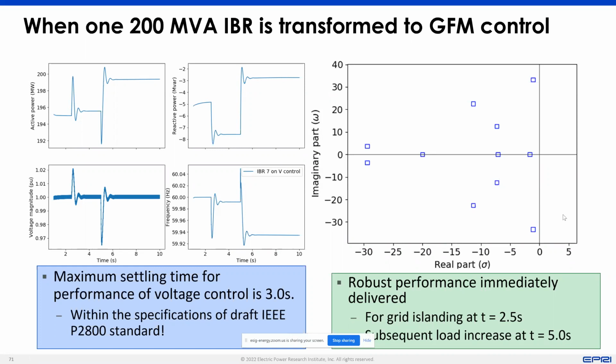There could be consequences of that in the future, in terms of once you have more grid following resources placed, the size of the grid forming inverter that you need to further stabilize the system later on could actually increase. And the implication is that maybe after a point, the cost to put that next grid forming inverter could be larger than what you could have put before.